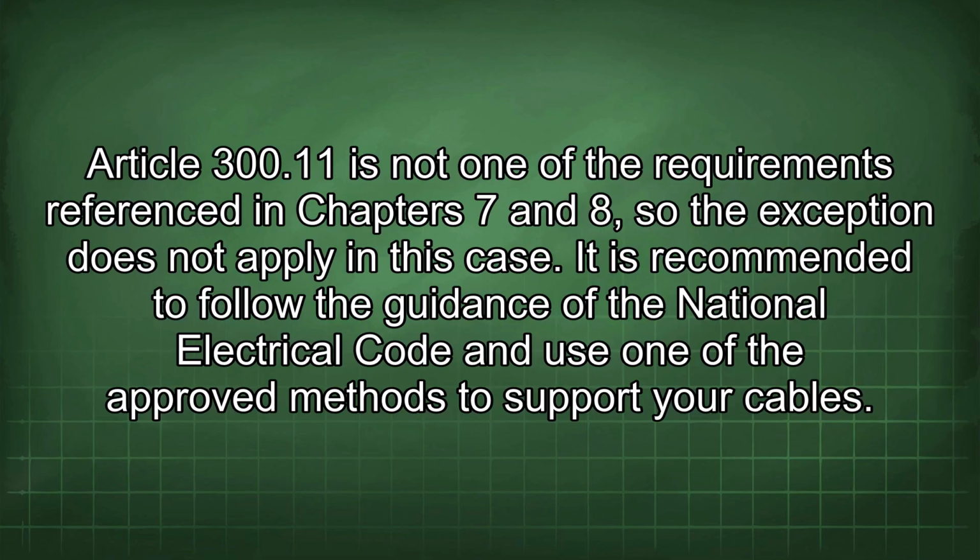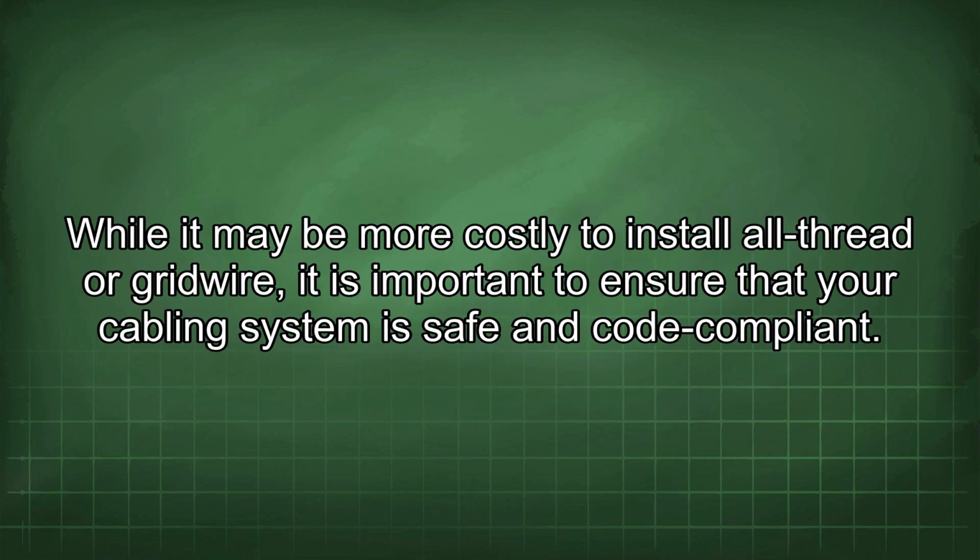in this case. It is recommended to follow the guidance of the National Electrical Code and use one of the approved methods to support your cables. While it may be more costly to install all-thread or grid wire, it is important to ensure that your cabling system is safe and code compliant.